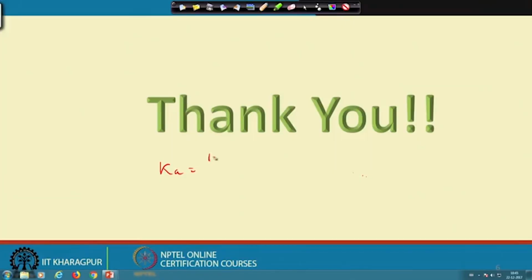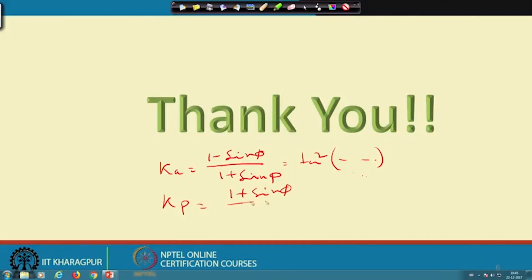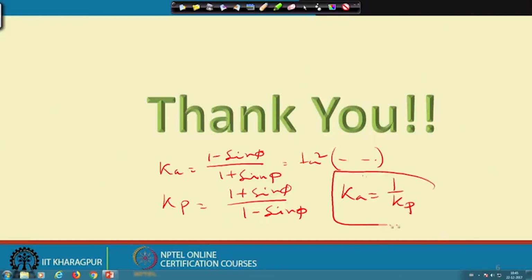Ka equals (1 minus sin phi) by (1 plus sin phi), or in the tan form, tan square (45 minus phi by 2). That formula we can also use. Kp equals (1 plus sin phi) by (1 minus sin phi). From there we can see that Ka equals 1 by Kp. This is another point to be remembered.